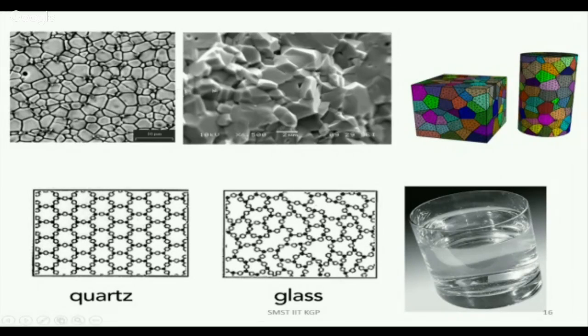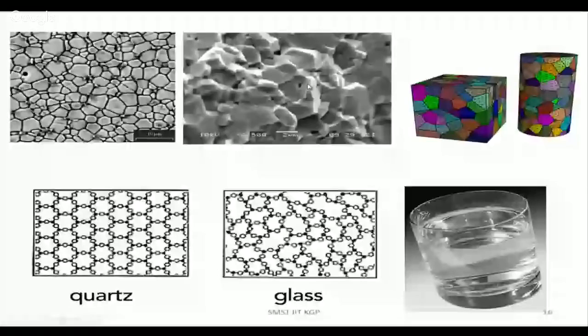And as you can see, the fracture surface of alumina, where you can see a three-dimensional view of individual grains, and you can see that there are intergranular spaces or voids, as well as grain boundaries, and also grain pull out, and even some kind of transgranular fracture as well as intergranular fracture. So these are different natures of the failure in the crystalline material.